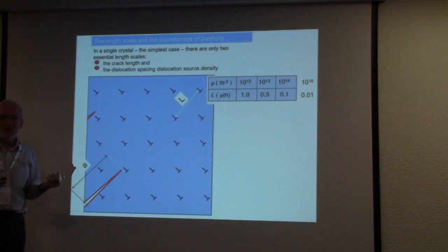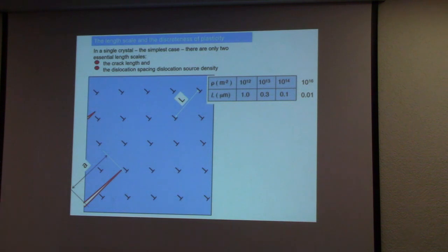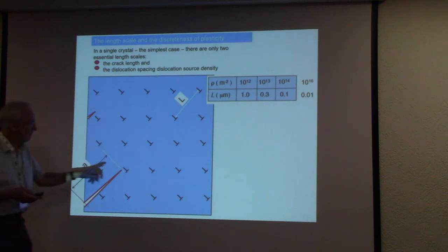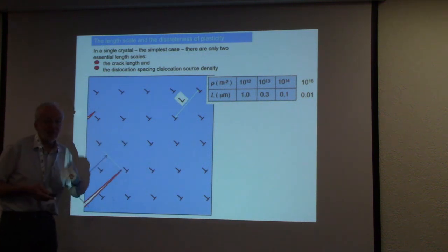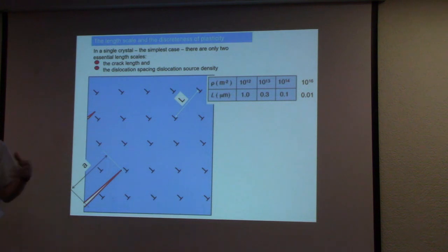In fatigue crack propagation near the threshold, the loads we apply are extremely low, the threshold being in the order of a few megapascal times square root of meter. In this case, the size of the cyclic plastic zone, if you calculate it, is in the order of a micron or below.